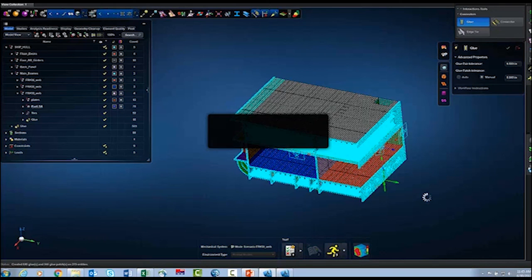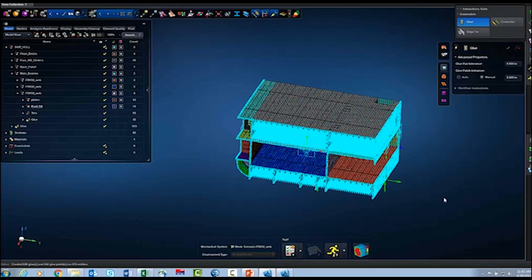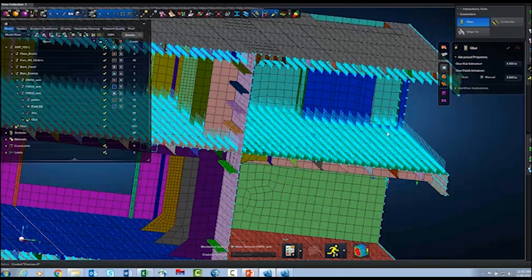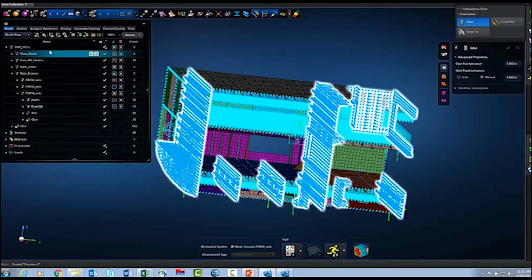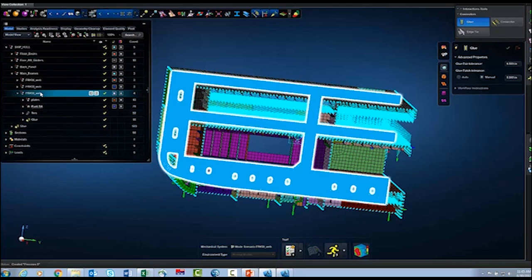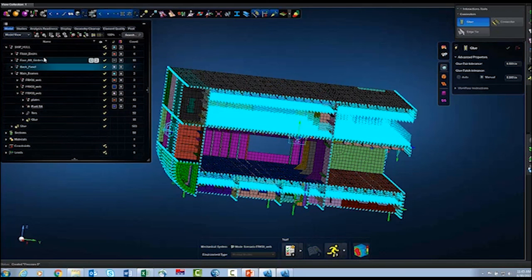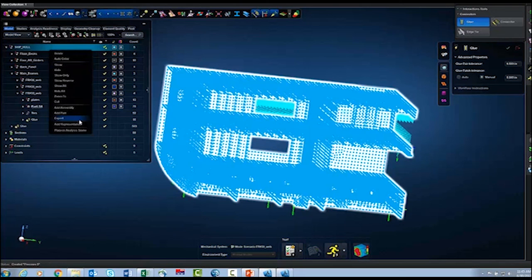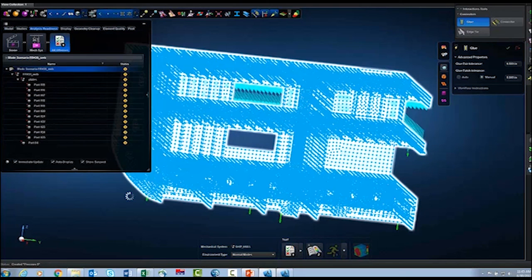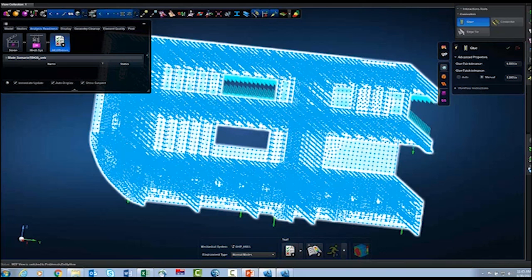So we'll put our loads and boundary conditions on here, and I've just got some pressures on each one of the floor decks here. All right, you can imagine I incrementally validated this one web. You can imagine that I incrementally validated the rest. I'm now ready to run the whole thing. Let's put it in the analysis scene. Let's let Apex check the model for me.